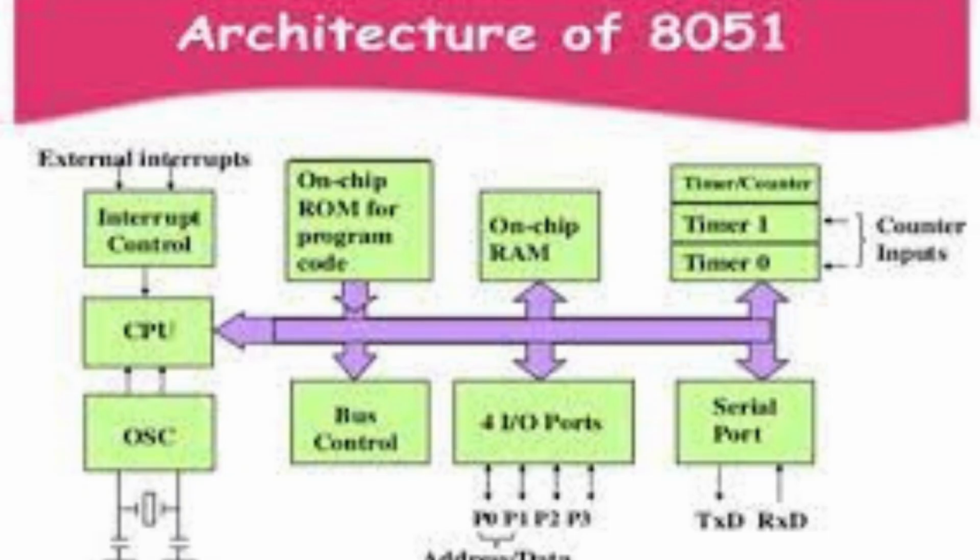The choice of microcontroller architecture depends on the specific requirements of the embedded system, such as processing power, power consumption, and memory size. Here's a detailed explanation of each microcontroller architecture. Harvard architecture. The Harvard architecture is characterized by having separate memory spaces for instruction and data. This means that the program code is stored in one memory space and the data is stored in another. This allows the processor to fetch instructions and data simultaneously, resulting in faster processing.